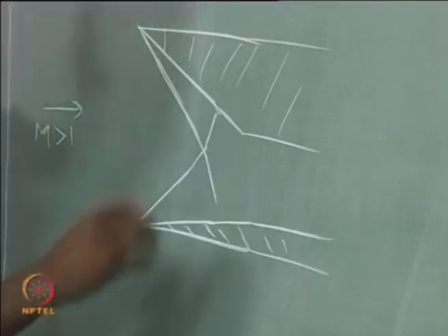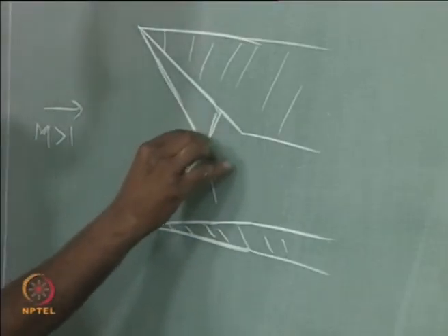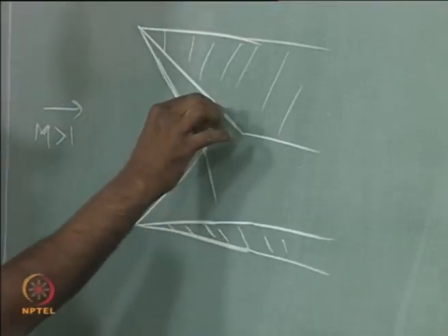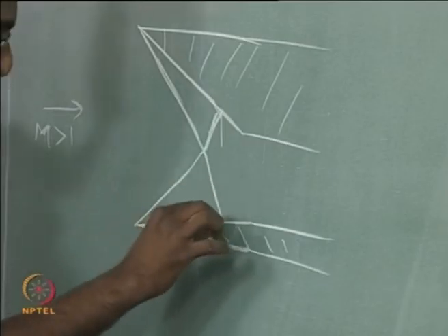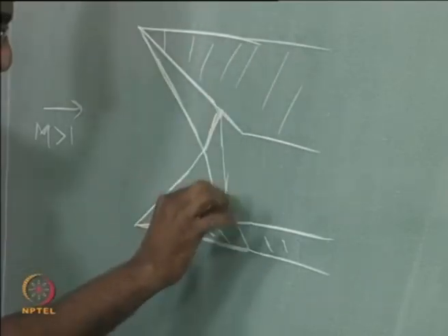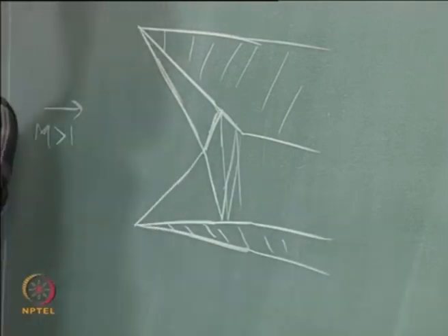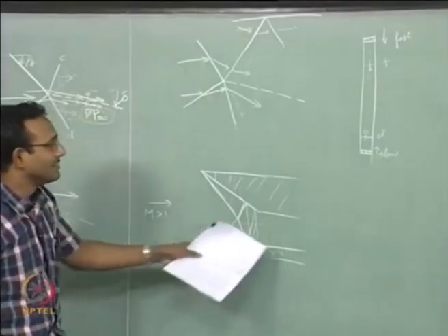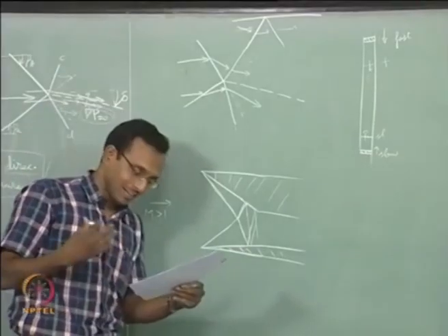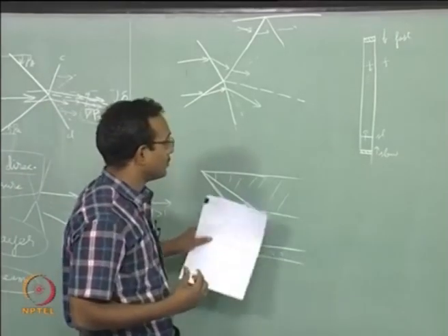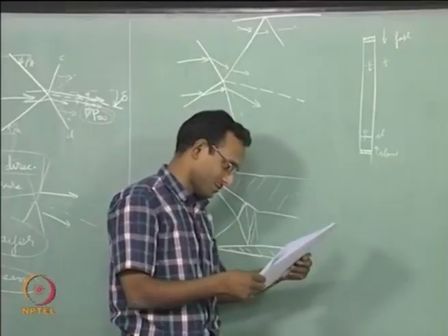Now when these shocks come in, whatever we did here will happen. After that, now I have to think about interaction of this shock with this wall, it will bounce off and come back, this will bounce off and come back. Now this will keep on oscillating like this several times. This is what they start calling shock trains inside. Okay. We will deal with this kind of intake problems later. Currently we will jump to some other problem after this.